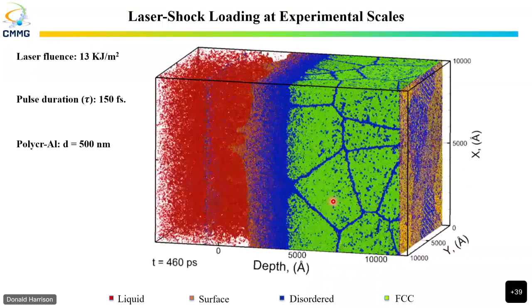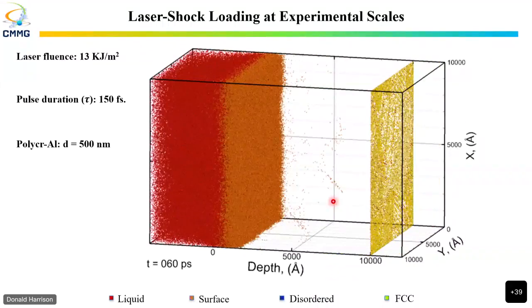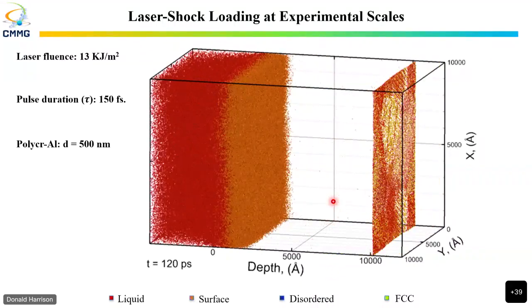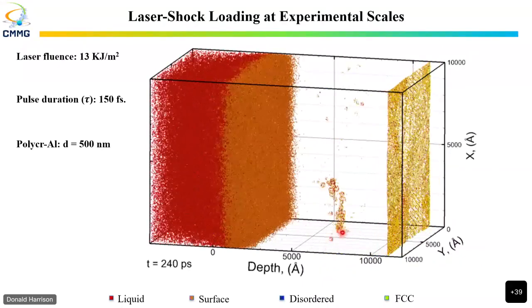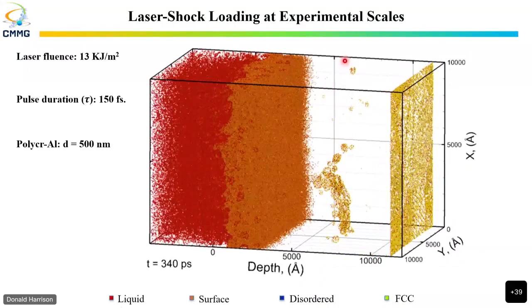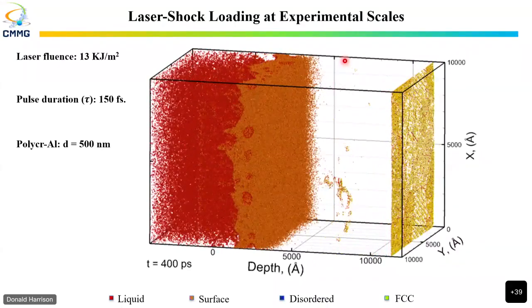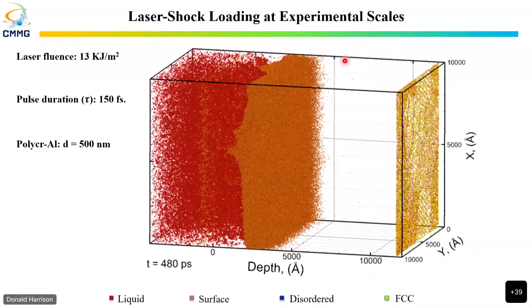And then we looked at the microstructure. Again, let me just blank out all the BCC and all the FCC atoms. What happened was, as the wave comes in and this starts to expand, you actually start seeing voids nucleating in the middle of the sample. But as the simulation continues to evolve, they go back and close. So if you're just looking at the microstructure from outside, you don't see any voids. You're like, okay, it did not spall at all.